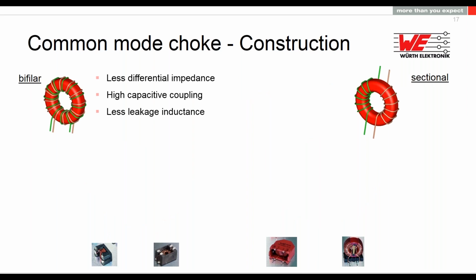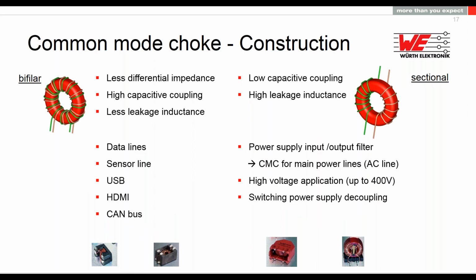Now, the advantage and disadvantage of the different winding methods: first, the sector wound one is a must if you have a high voltage separation. If you have an AC voltage of 230 or 400 volt, you don't want to have a leakage of the voltage, and you will need a separation distance by the norm or by the law.